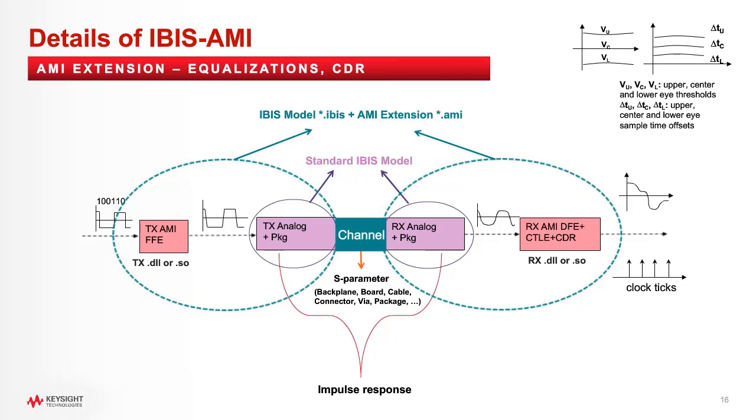Based on the choice of simulation modes, such as bit-by-bit or statistical, and the existence of an AMI gateway function, there are several different calculation processes, but mainly through either a convolution process or the stochastic properties of a conceptually infinite bit sequence, where in fact there is no bit pattern per se.